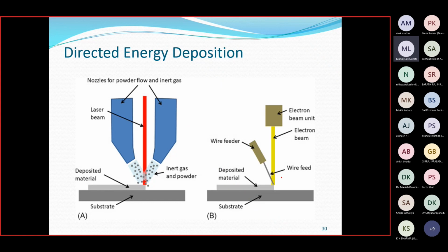Another way is also used by some printers, but both are the same and come under directed energy deposition. In this, you are depositing heat. The wire feeder or the powder will come, not an issue, but the heat is deposited, meaning this beam will be given to positions. The nozzle which is providing heat, electron beam or laser beam, will move from one place to another place.